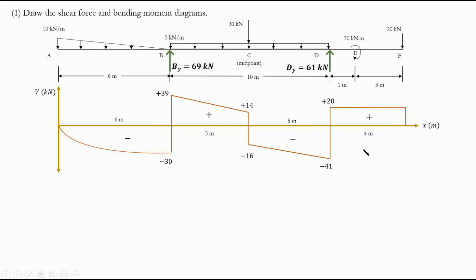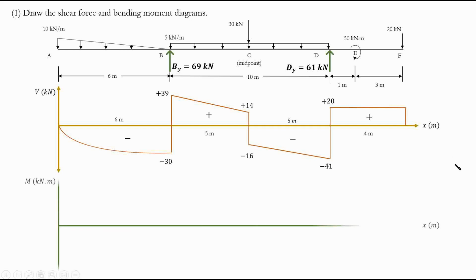Okay, now we are prepared to draw the moment diagram. So we draw the moment diagram based on the shear force diagram. Of course, the units are kilonewton meters. And let's start. So the same concept that applied from the load diagram to the shear force diagram will apply from the shear force diagram to the moment diagram, right?